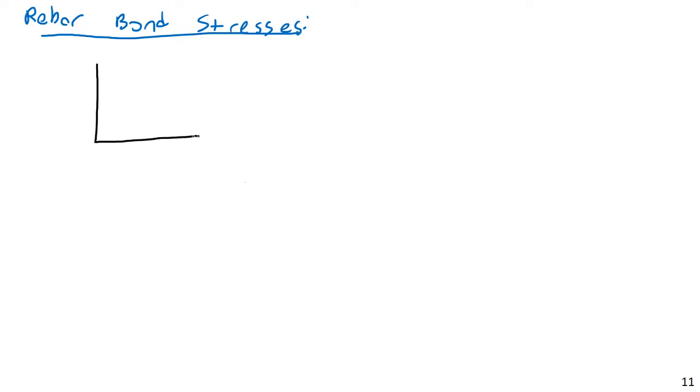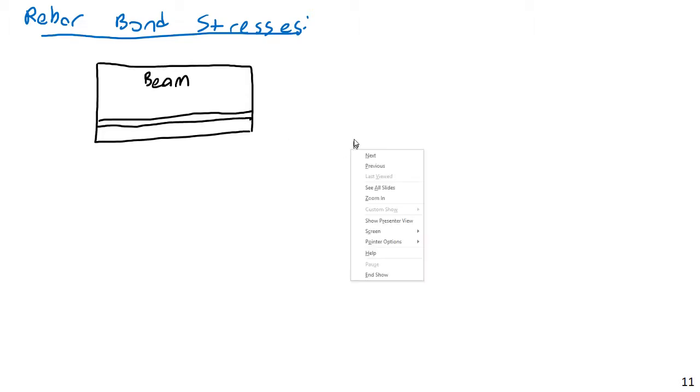So if you're looking at a reinforced concrete beam, say some beam here, and this is your beam, and if we're considering this as positive bending, so we have our rebar here, well, you would have compression at the top in the Whitney stress block and tension on the bottom in the steel. So compression up here in the Whitney stress block and tension down here in the steel.